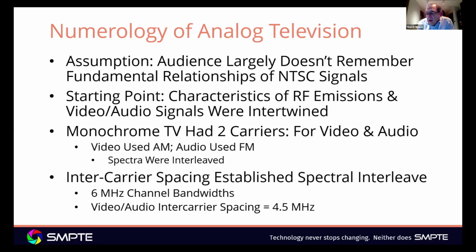So we've got a direct connection between what we do in the video content and what happens in the spectrum because of the impact of the line sync and the energy that comes with each line and modulates the signal effectively at harmonics of the line rate.